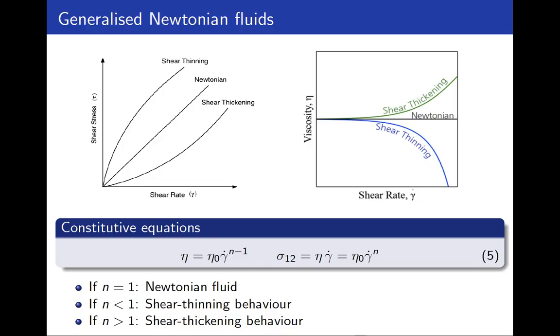But the longer you apply the force with your hand, so you are applying a force over the brush, and with this brush you are applying the paint over the wall, so you are applying a stress because you are applying a force over a surface, you will notice that the viscosity of the paint is going to decrease. You will notice how it is becoming easier to paint, because the viscosity of the fluid is decreasing. So that's a common example of a shear-thinning fluid.